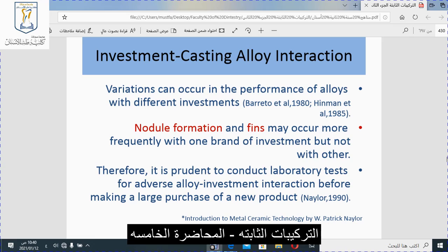Sometimes we have to do venting for base metal, for phosphate bonded investment or silicate bonded investment, to completely evacuate the gas from the mold and prevent the formation of nodules, or back pressure porosity or suck back porosity. In case of gypsum bonded investment, there is high porosity, so this problem is well tolerated. So we do not need to do fins, or the auxiliary sprue or vent.